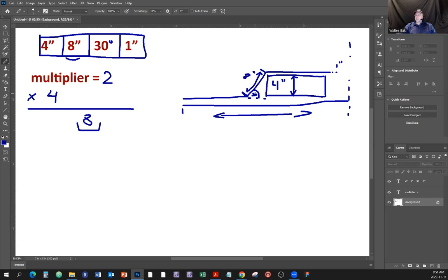If we bend that 30 degrees, then flip it around and bend it the other way 30 degrees, this travel is going to be, if we travel 8 inches, we're going to go 4 inches high. If we go further, we're going to go higher, right? But we want to get 4 inches. There you go. 8 inches is the distance between the two bend points. And then it says that the whole pipe is going to shrink 1 inch.